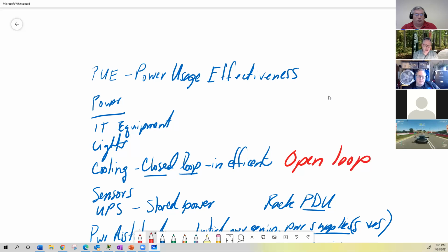Yeah. Well, what we found is an optimal range. Data centers usually try and stay at around 67 degrees Fahrenheit. The air coming in is that temperature, and to keep the equipment cold, it can't go down to freezing. But there are environmental conditions that the server has to run in, and it shows it in the user manual. When you buy it and unbox the server, it says this has got to be under 10,000 feet. It's got to be between this temperature and this temperature. It can't be too cold and it can't be too hot, but it's a very wide range.